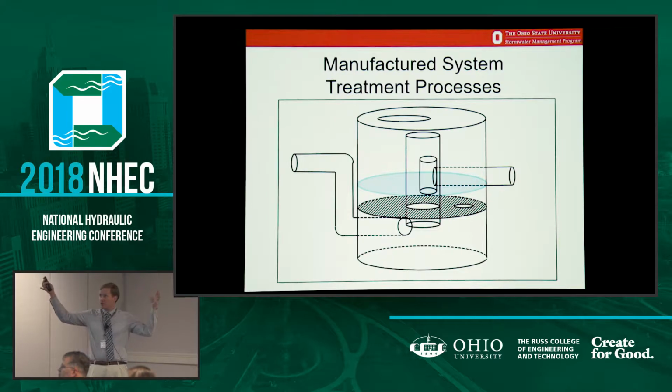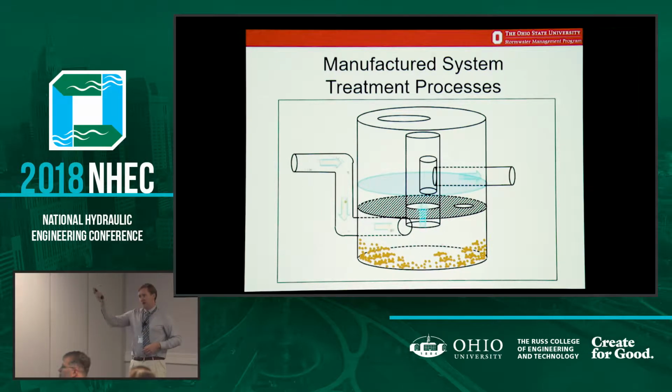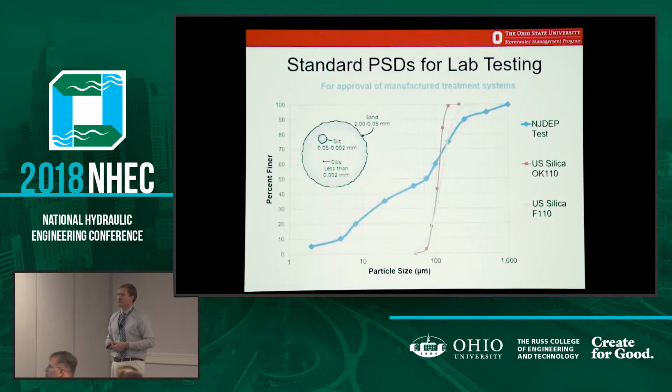It's basically a large cylindrical tank that gets put in the ground. The stormwater comes in through basically a centrifugal force type of situation. The sediment and a lot of the trash is accumulated in the bottom. Then the stormwater goes up and out through the outlet into the storm sewer network. And then you come in periodically, typically once a quarter, and suck all that out with a vac truck. Okay, so that's the maintenance that's involved, relatively simple maintenance.